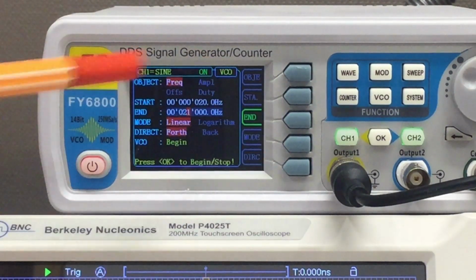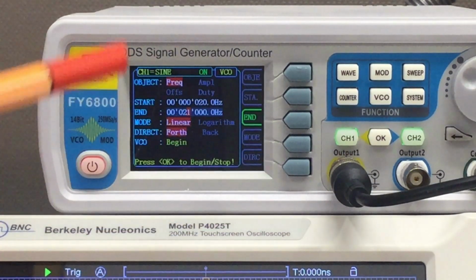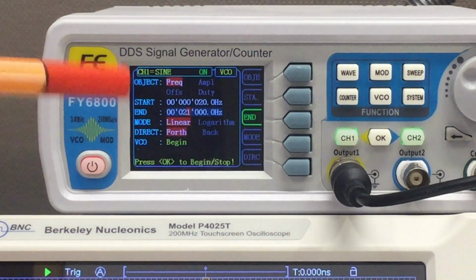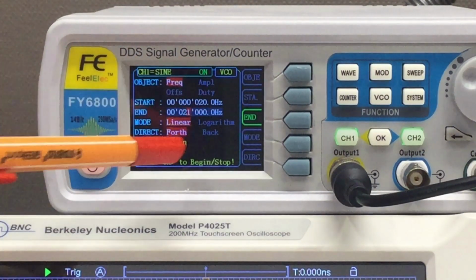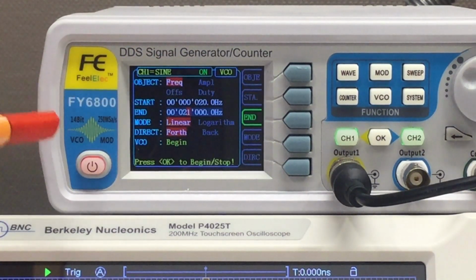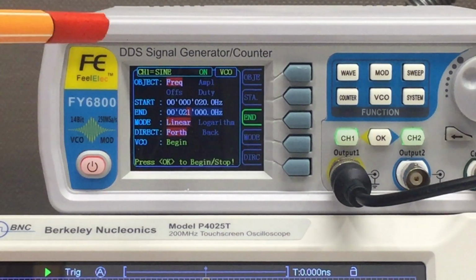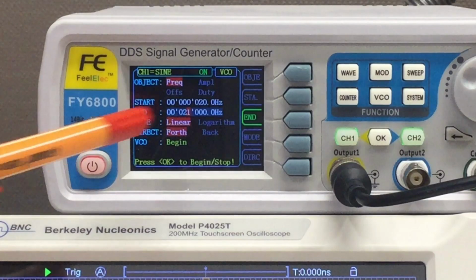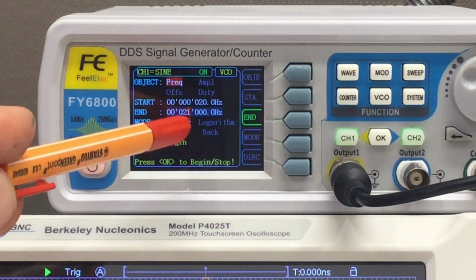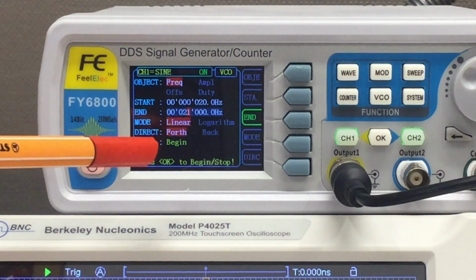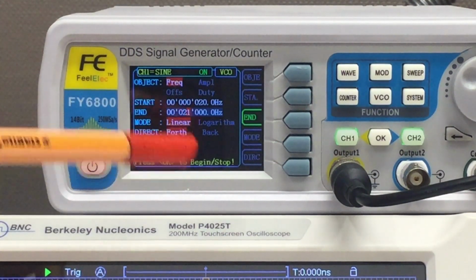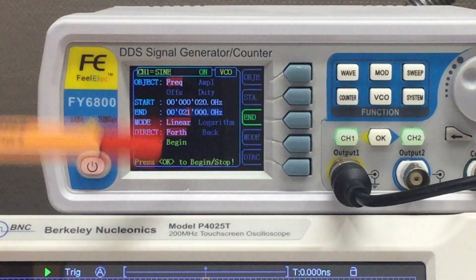Or he has a unit with another firmware, or I don't know. Anyway, with these settings, I can coax the VCO in here to give me a frequency between 20 Hertz and 20 kilohertz with an input voltage between minus 0.085 volts and 5 volts.